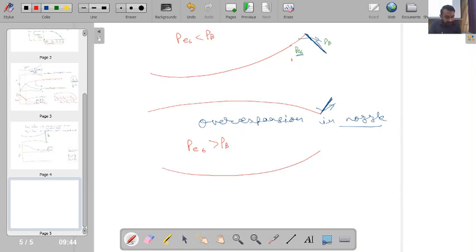So in this type of situation, what happens? Say if you are not able to precisely control the pressure at the nozzle exit, and if it is slightly greater than back pressure, then I will be having formation of a series of Mach waves. So what do Mach waves do? These also lead to a decrease in the pressure of the wave. So here I will be finding that through these Mach waves, I will actually have further expansion of the flow, and here pressure will be PB and here pressure will be PE6.